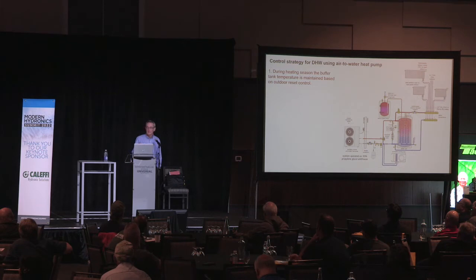When you come out of domestic water heating and you go back into chill water cooling, you've got to be careful. Anybody know what could happen? Think about it. The heat pump's sitting there running at maybe 125-degree water temperature, and all of a sudden you just move that diverter valve. What's immediately going to flow to your chilled water coil? 125-degree water. And that's not hard to get around.